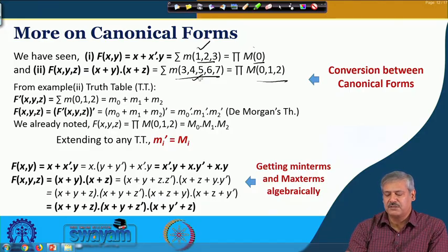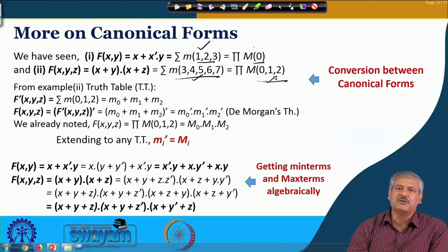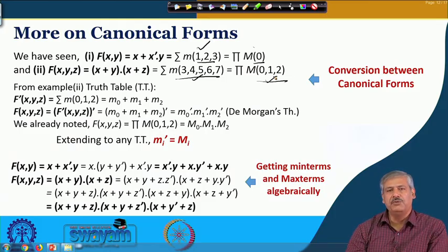So, if 5 are taken in the Minterm based representation SOP, the remaining 3 are taken up in the Maxterm based representation using POS form, product of sum form. So, the whole set minus one form's representation, whatever the corresponding decimal equivalent places, the remainder goes to the other form. That is the way we can quickly convert from one form to another.